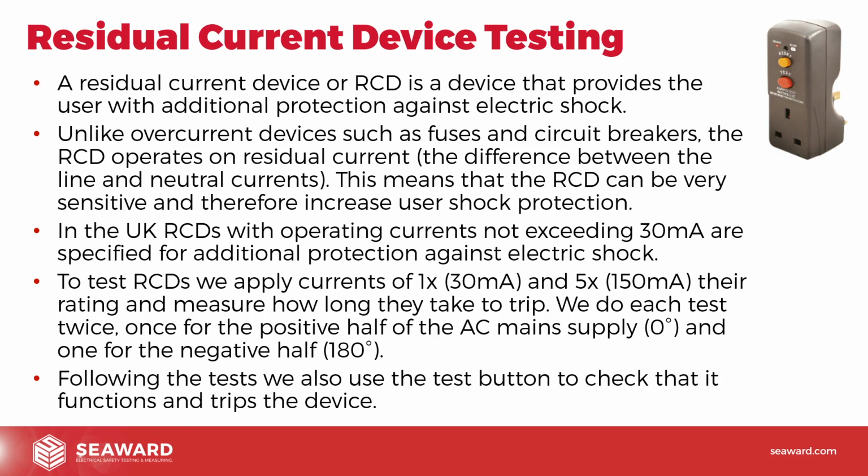When users do a user inspection, a user check, they would just use the test button as part of their user check to make sure it works. They wouldn't actually test the tripping times like we would when we're doing a full combined inspection and test. So that's why we always say check the test button at the end, because we don't want to influence the other results by just pressing the test button, and we've masked a fault that was there and we've hidden it, and it'll obviously then just come back after a little while. The thing will corrode up again, it'll rust up and it'll stick. Always an important point that we do the functional check afterwards, not before we've done the measured tests.